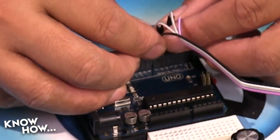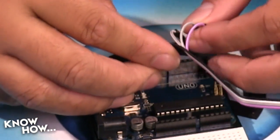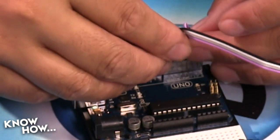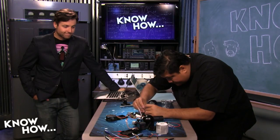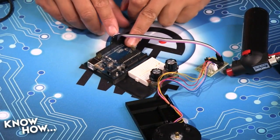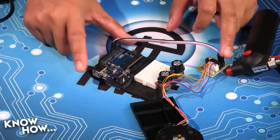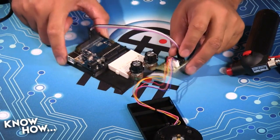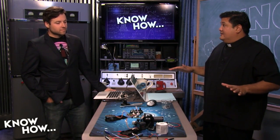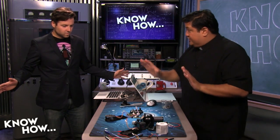Precisely, exactly. And actually, very good point. All that matters right now is order, because I can always redo my programming. Now, why am I having so much trouble here? There we go. So again, I'm going purple, gray, white, and black. Purple, gray, white, and black. So it's in the right order. Believe it or not, that's it. That's it for connecting to the Arduino. I just need those 4 pins.